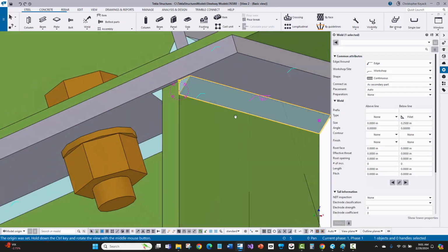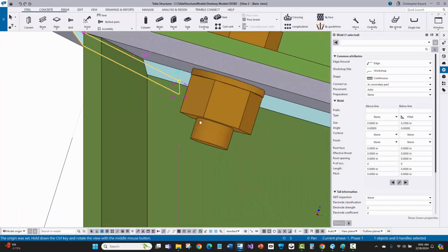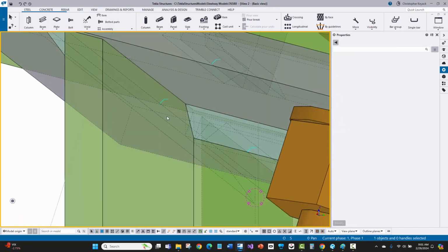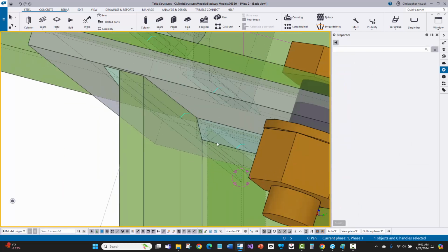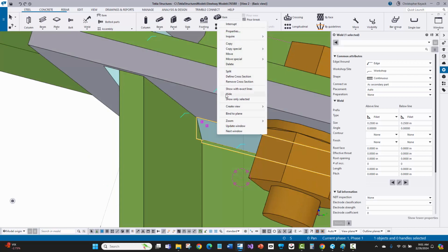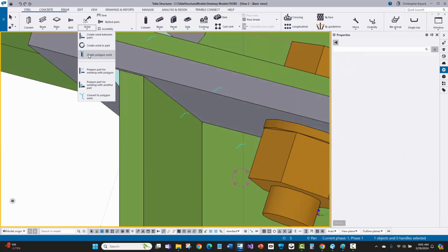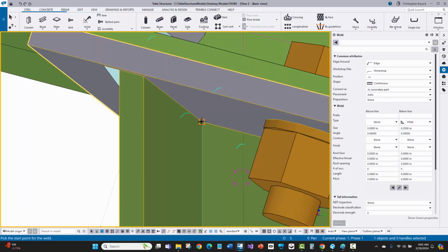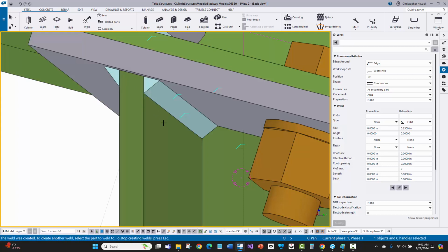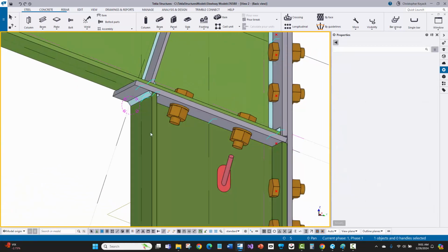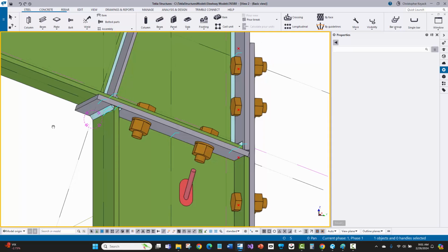And then just on the other side here, what I'll do is I'll weld in there just like I did on the other side. And so this is where you got to be careful in 3D because you see a lot of stuff going on here. So sometimes it's actually easier to do solid. Select that web weld and just say hide, so that way it's not in your way. Then you can come back to the polygon weld and then pick your 2 parts. And then we'll pick those inside corners where it's nice and easy to see because we hid the web weld. And then there we go. And then just one more weld to do down there at the bottom, but that basically shows you that process.